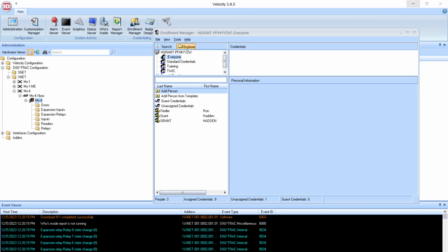Extended Access is a special feature specifically designed for ScramblePads which allows the person who enters a code to decide how long the door will be left unlocked behind them. The default door mode time is 6 seconds, and the door open too long time is 12 seconds. This tool extends that time to a max of 1,440 minutes.